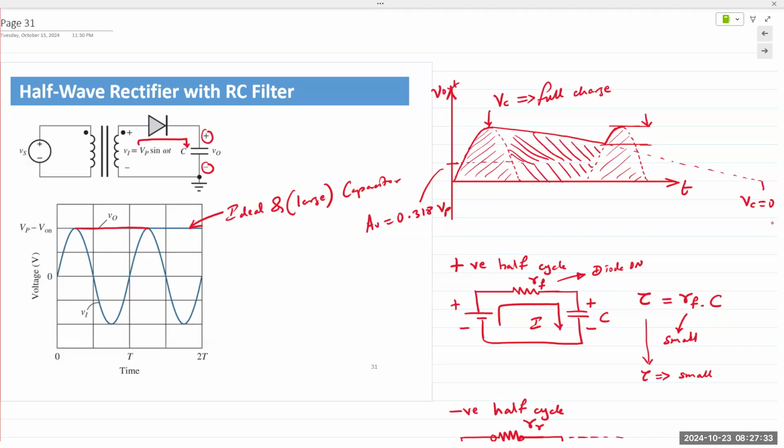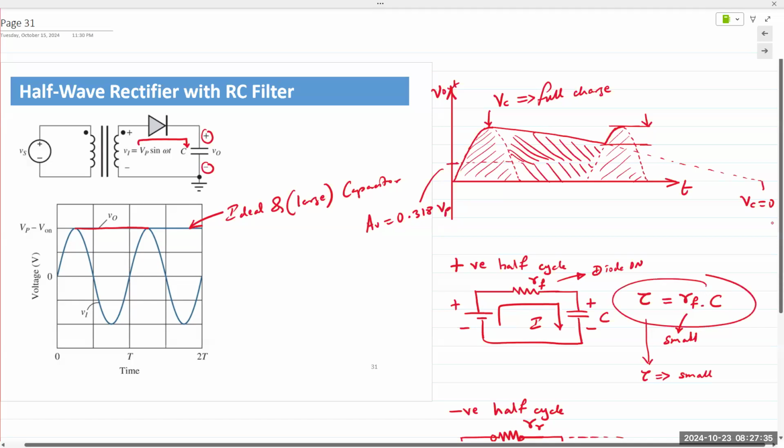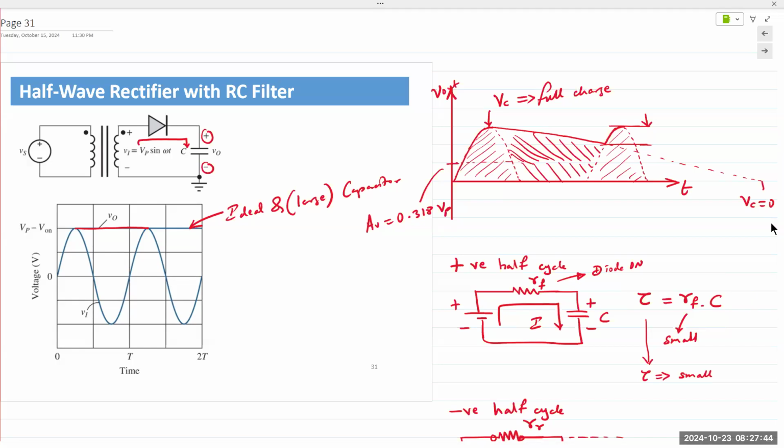Because if it is too large, then the time constant during charging is also large, and it may never end up reaching a full charge, which is a possibility. So there is a fine line between trying to get it large versus keeping it small enough so that it reaches full charge. But again, this has been in existence for decades.